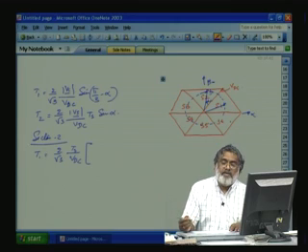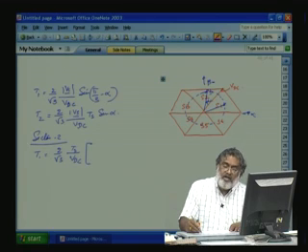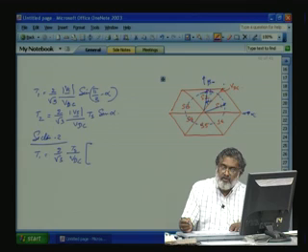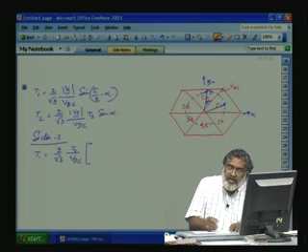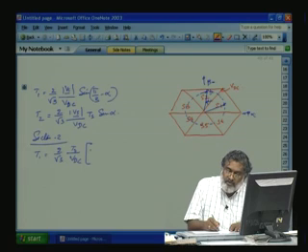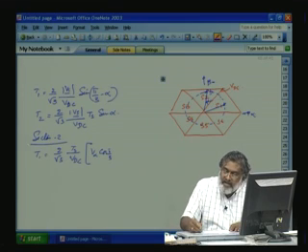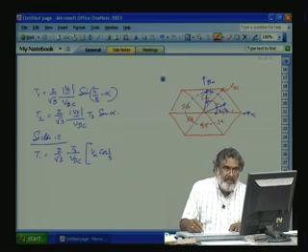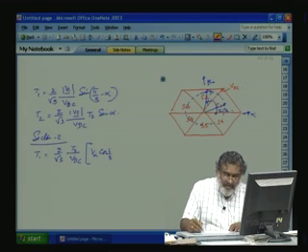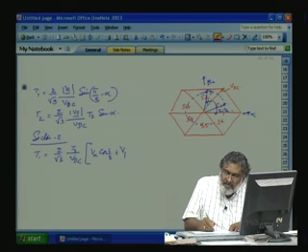We are taking it in terms of our alpha beta components. That means when converting from 3-phase ABC to alpha beta, alpha is fixed along this axis, beta is fixed along this axis. So the component along the start of sector 2 will contribute from both alpha and beta. That is what we were talking about, the Vs cos alpha type, which is equal to V alpha cos pi by 3. This angle is pi by 3. How much will V beta contribute? Pi by 3 means 60 degrees, so this will be 30 degrees. V beta also contributes, that is V beta into cos pi by 6.